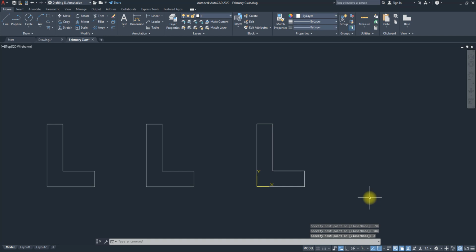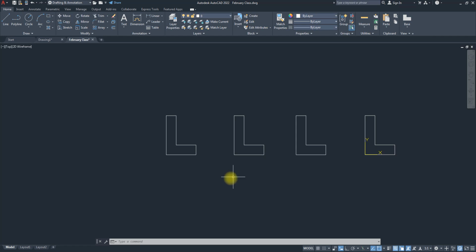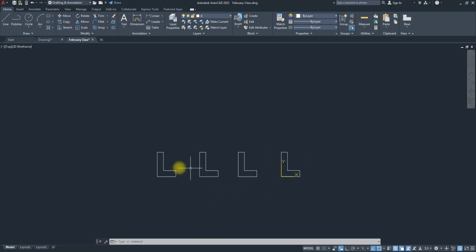You can see that I did not do any adds and I did not do any less than. That's just the advantage of dynamic input. But aside from this, it slows down the system, so I don't like using it. But that doesn't mean I should not tell you. If you now feel you want to use it, fine. Do you understand? So now we've been able to do the absolute, relative rectangular, relative polar, and dynamic inputs for this L shape.